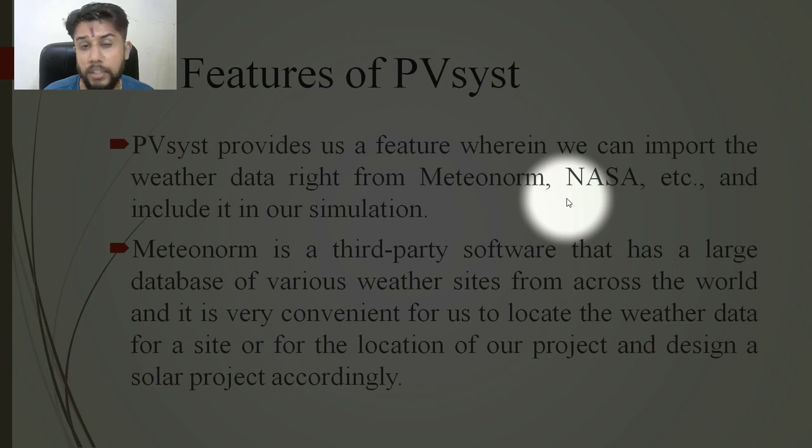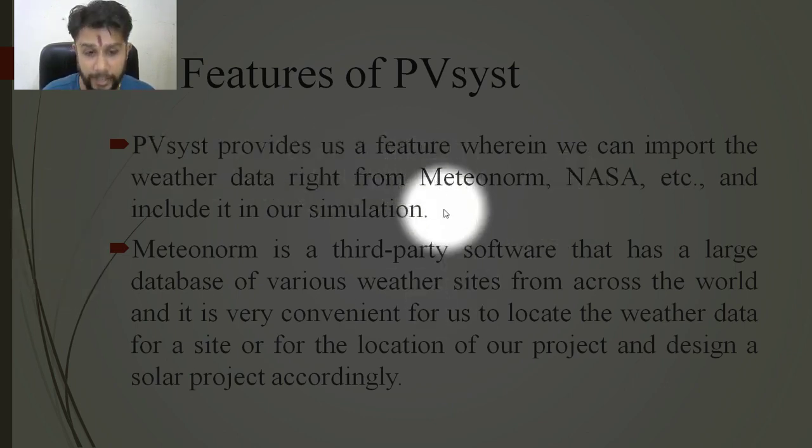Meteonorm is third-party software. It has a wide range of database for the weather at different locations available across the globe. So whatever location you choose, you can easily find the Meteonorm data for that location with the help of this Meteonorm data tool. So we need to incorporate this meteo data for the exact amount of generation, to make the simulation more realistic.